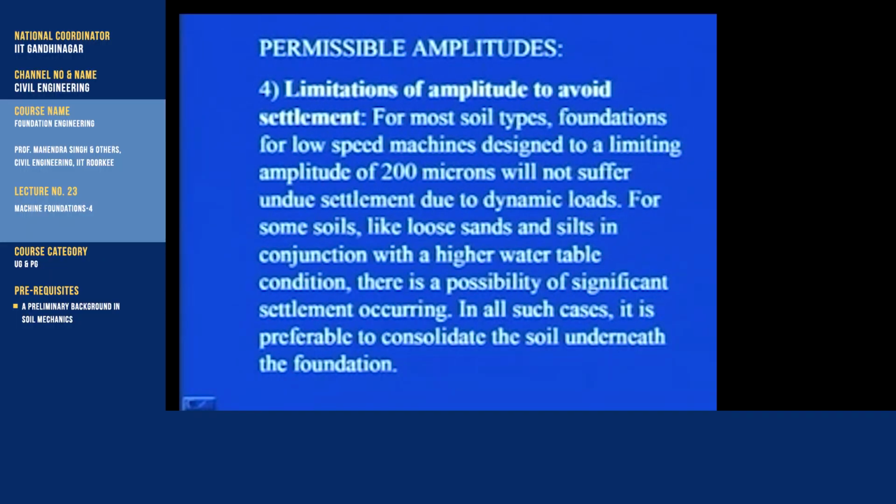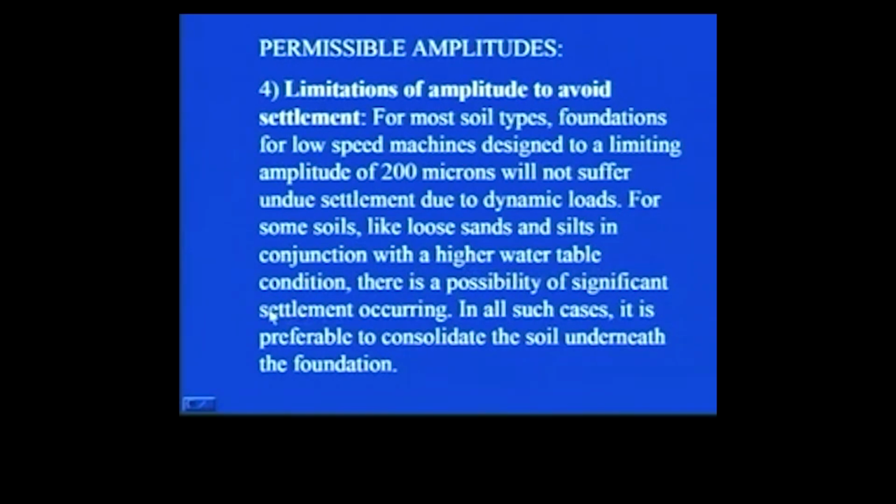So, usually if you are designing the machine for the frequency corresponding to an amplitude lesser than this 200 microns, they will be safe for the settlement. For some soils like loose sands and silts, in conjunction with the higher water table condition, there is a possibility of significant settlement occurring.